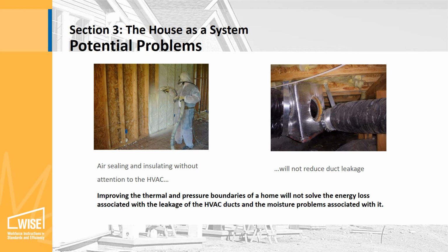Air sealing and insulating without attention to the HVAC system will not reduce energy lost through a poorly sealed duct system. Getting the heated or cooled air where it needs to go is just as important as improvements made to the thermal and pressure boundaries.